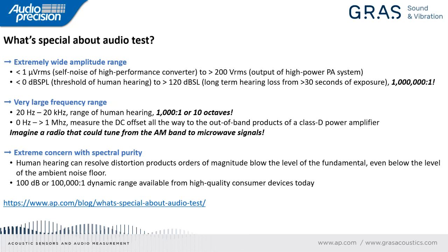So it's really this very, very large amplitude range, and we can't statically compensate for it. You know, on an oscilloscope, you might change from a 10x probe to a 1x probe, but here we're talking about a continuous AC signal, and that dynamic range could change, you know, instantaneously.